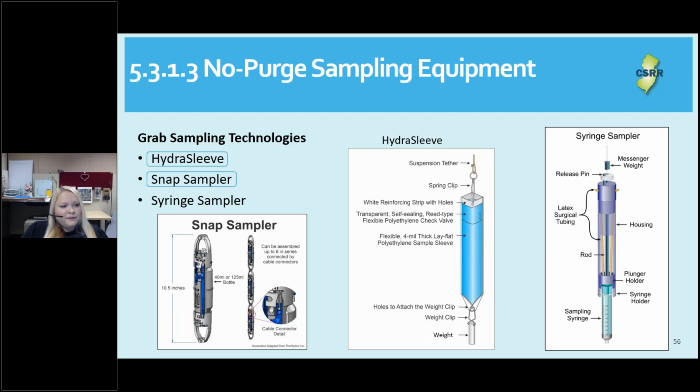One of the advantages, it is a fixed system, so samples will always be collected at the same depth because that whole assembly will go back down to the same depth as before. They do have a 2-week deployment period that is recommended.